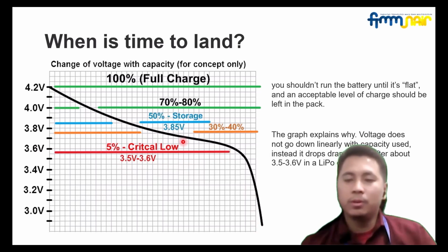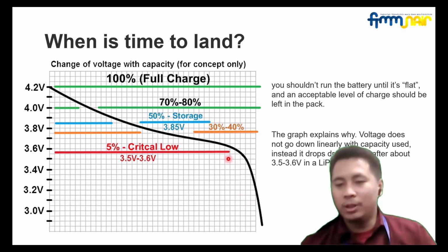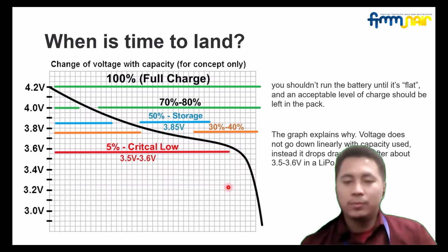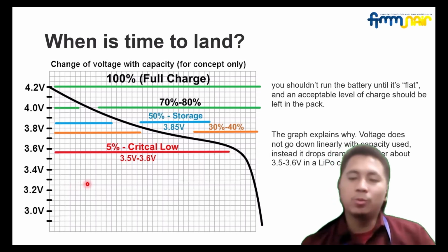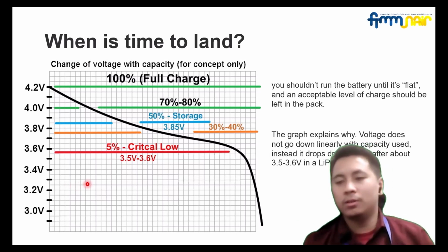Yeah, it will drop. It may drop to zero voltage, and that is very dangerous for the aircraft. If it is pointing down like this, the voltage will drop, the system will shut down, and the drone will fall.